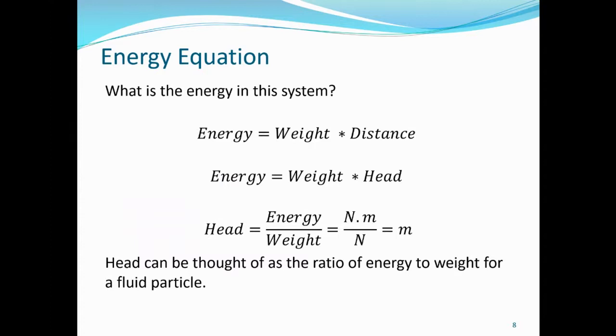The energy, as we have mentioned, is weight times distance, which is simply weight times head, because head is simply height. Distance can also be expressed as height. So weight times head. So head is simply energy per unit weight. Head is simply energy per unit weight.